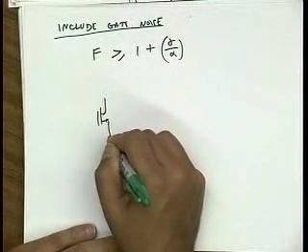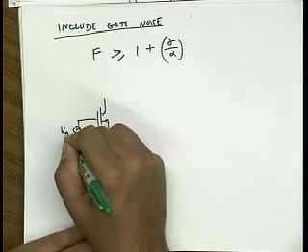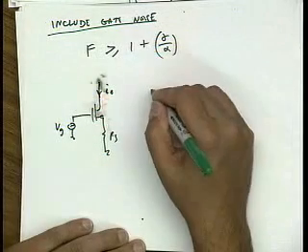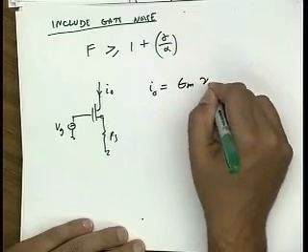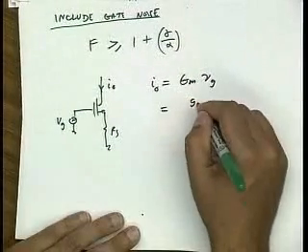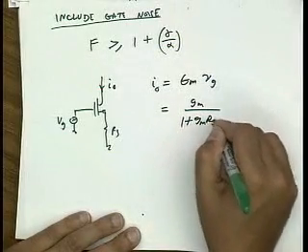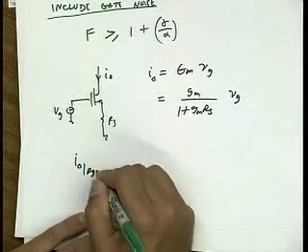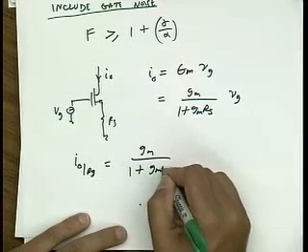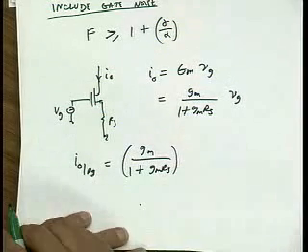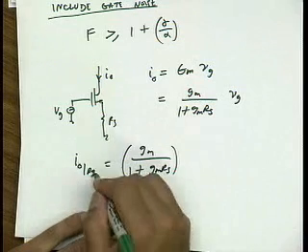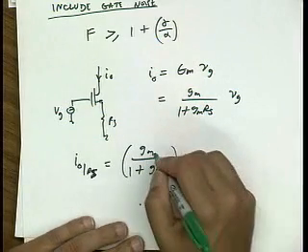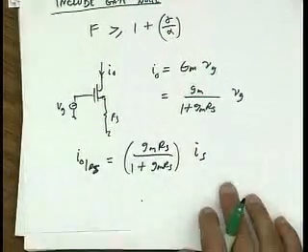So if I come back to my circuit and only include my gate noise, then this is quite simple, right? Because this is just a degenerated amplifier, so I don't have to write any equations. The output is just Gm times VG, where Gm is the feedback-degenerated Gm of the device. So the output noise just due to RG is going to be Gm over 1 plus Gm RS. The output we found on the previous page due to the source is actually Gm RS over 1 plus Gm RS times IS, right?